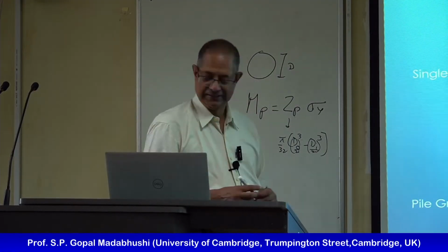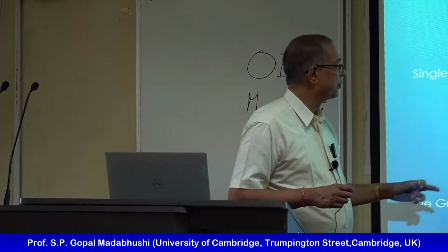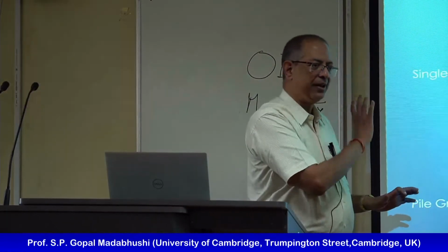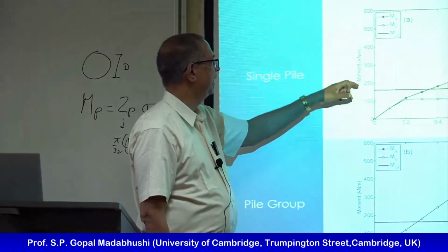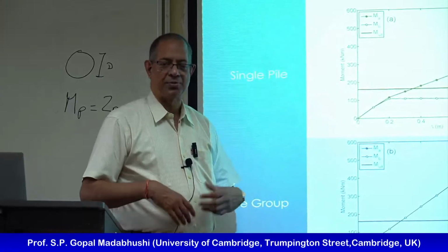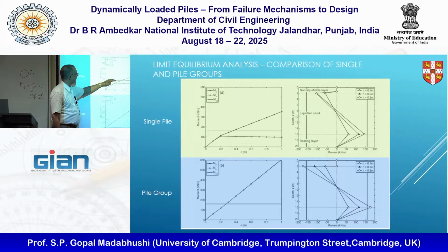Anyhow, so radius of gyration also comes into it. Okay, so that we know, and for this it was calculated at about 180 kilonewton meters for the experimental pile. Then we had an aluminum pile, calculated the ZP for that and the yield stress, and then converted that into prototype scale using the scaling laws we learned yesterday. So that is the limit.